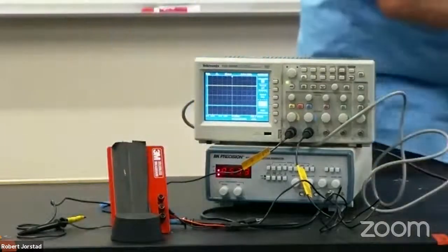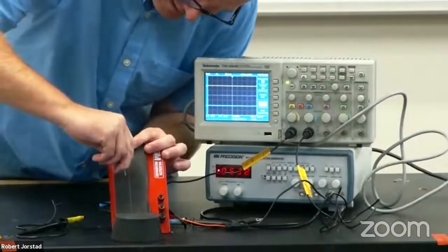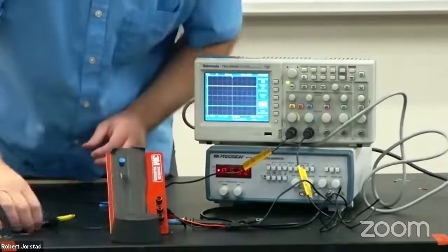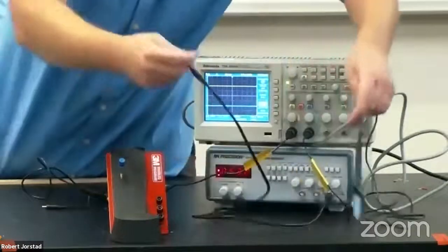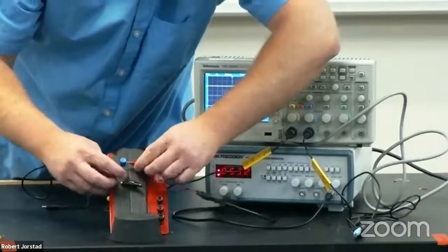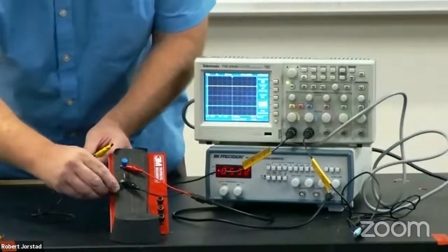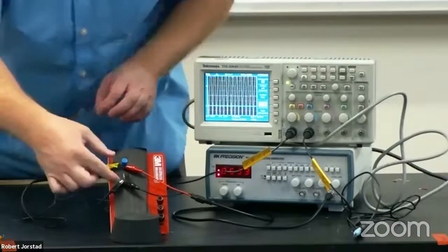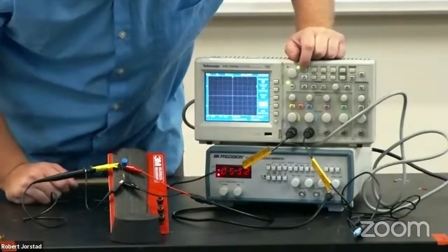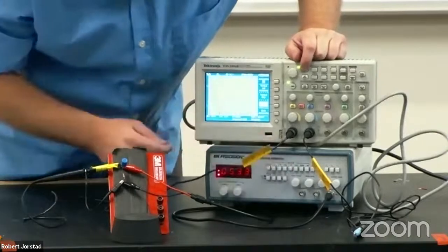So let's get this out of here. Just putting these things in series for right now. And then I'm going to first apply the voltage and then measure stuff. Okay, now these might actually be different measurements. This one is going across the entire circuit. So the yellow thing on your screen, let me auto range really quick. Go. And actually, let's go up to 5 kilo and then auto range.